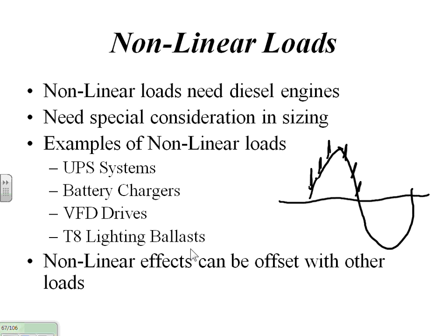I had a situation where I had a natural gas engine and an SCR load, and gas engines and diesel engines react differently to loads. These signals sometimes get fed back from the output of the generator, the output waveform. They have what they call a shunt excited set. They'll actually couple a portion back to the voltage regulator.